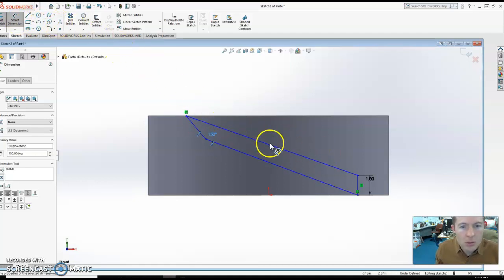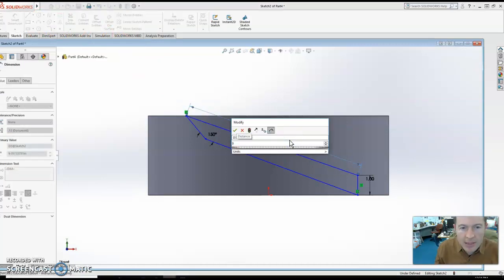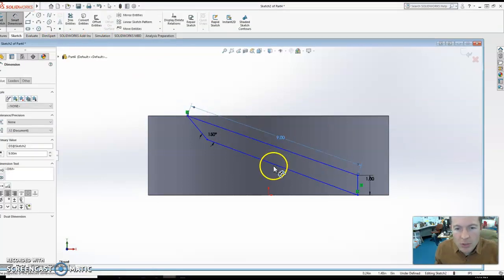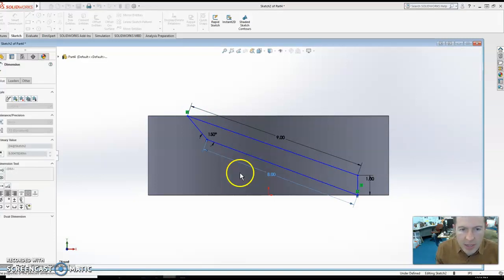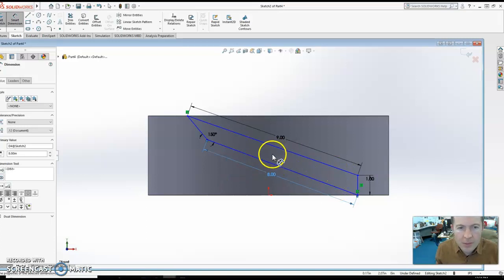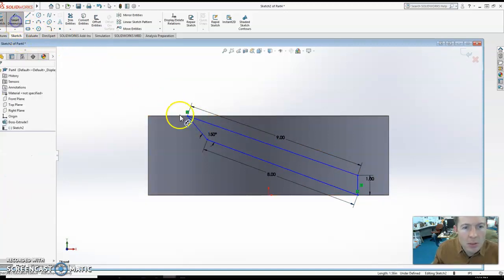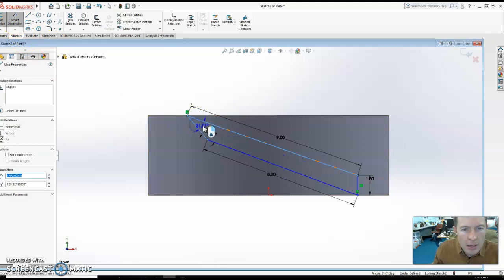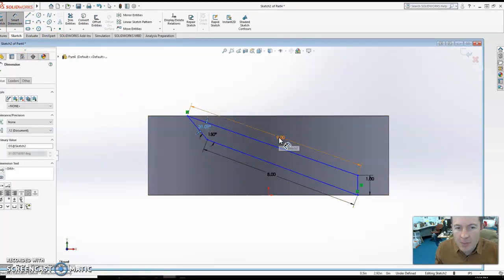Let's also do a dimension here. 9.06, that looks pretty good. I'm going to set it right at 9 using the dimension tool. Let's see what dimension this is. 8. Let's just leave it at 8. That looks pretty good. Just to see what this is, we don't have to necessarily do it, but another angle here. Let's see what this angle is between those guys. Smart dimension, there and there. Saying about 31. Saying that's already driven. That's fine, I don't mind that.